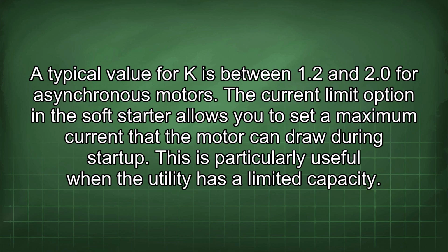The current limit option in the soft starter allows you to set a maximum current that the motor can draw during startup. This is particularly useful when the utility has a limited capacity.